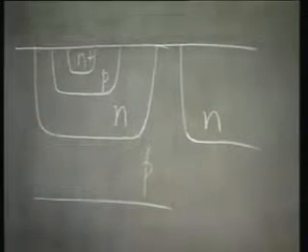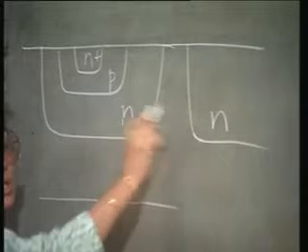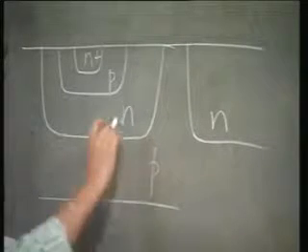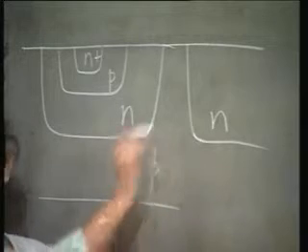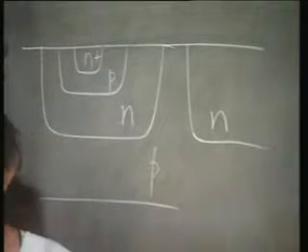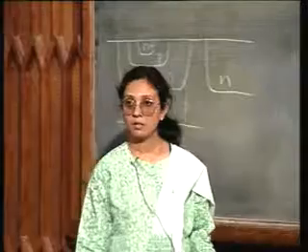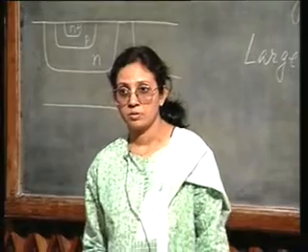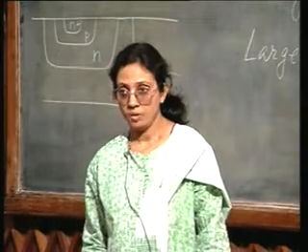the next adjacent transistor housed in another N diffusion. So, you see they are automatically isolated. I do not have to have this large p isolation diffusion. Okay?